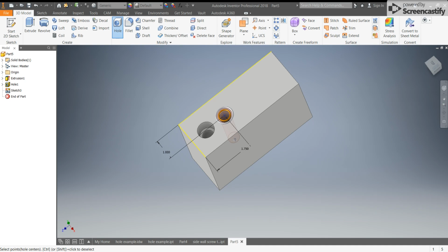And we still put the diameter of the wider part of the hole. I'm going to make that 1 inch this time. So it starts at a 1 inch diameter. It's going to take an 82 degree slope and go to a 1/2 inch diameter. So it's going to start at 1 inch and it's going to slope 82 degrees to a 1/2 inch.